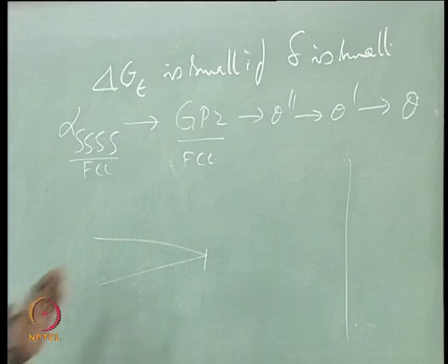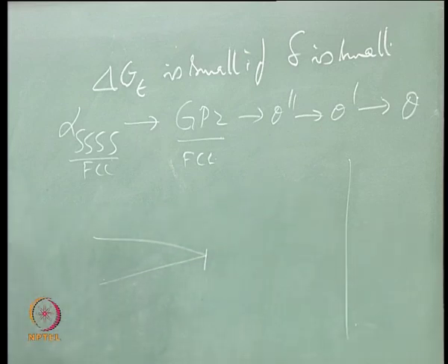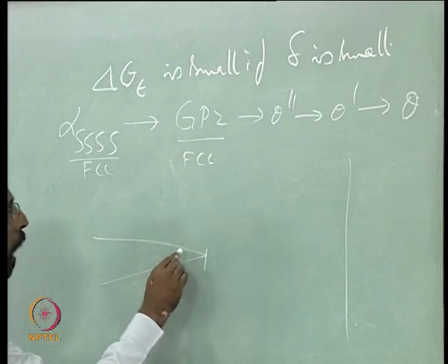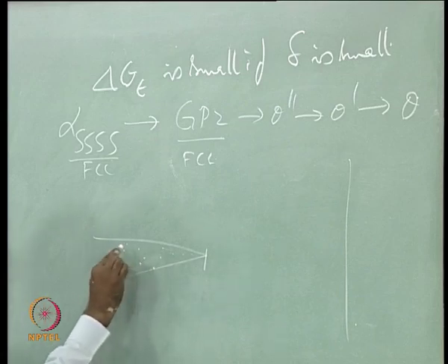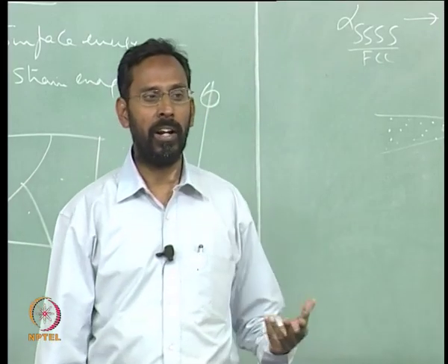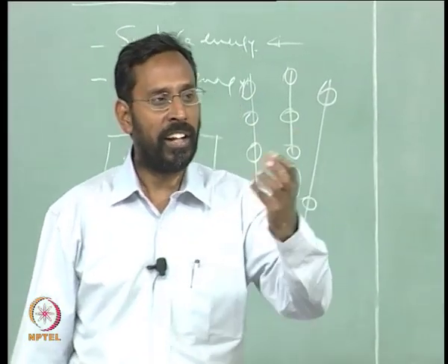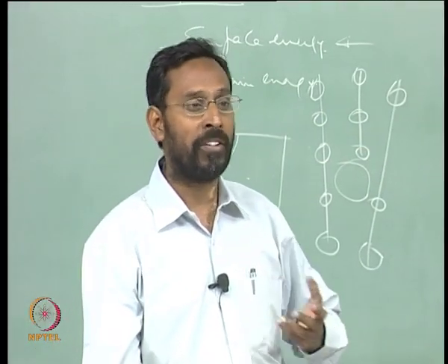If you do layer by layer sputtering and keep on detecting atoms and storing them, when you reconstruct the whole thing, you will be able to see how the atoms are distributed inside at a nanometric level. There you can see if there are any small clusters of copper or of iron or whatever it is, and people regularly see this. For example, carbon atoms going and sitting near the dislocations, we call them Cottrell atmospheres.